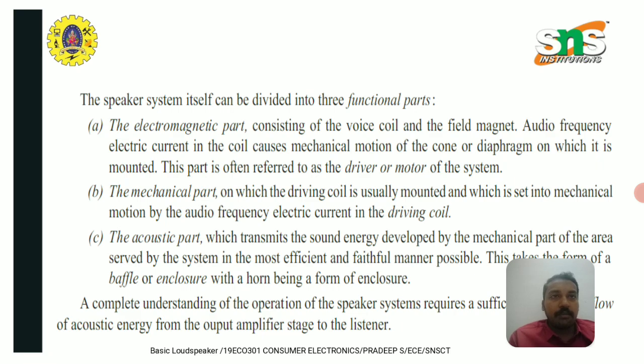The speaker system itself can be divided into three functional parts. The first one is the electromagnetic part, which consists of the voice coil and the field magnet. Audio frequency electric current in the coil causes mechanical motion of the cone or diaphragm on which it is mounted. This part is often referred to as the driver or motor of the system.